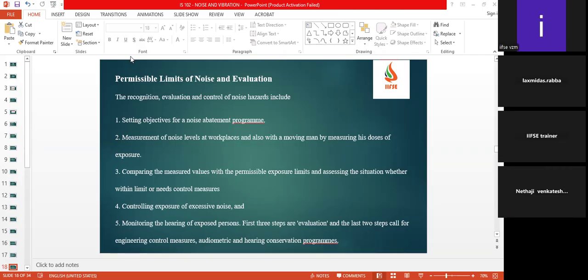So if it is 95 dB, we can work only 4 hours. If we use earplugs or earmuffs, then the working hours can be increased. Yes, you can. That's where we calculate this noise dose. In such a case, you should have solid evidence that after the use of your earplugs and earmuffs, what sound level you are effectively reducing. Then based on the result with the earplugs and earmuffs, you can calculate the noise dose, the exposure. Then you can define the time he can be exposed in that workspace or work area.